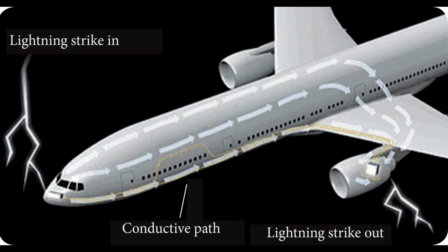In a composite aircraft, fiberglass is an excellent electrical insulator, while carbon fiber conducts electricity, but not as easily as aluminum. Therefore, additional electrical conductivity needs to be added to the outside layer of composite skin. This is done typically with fine metal meshes bonded to the skin surfaces. Aluminum and copper mesh are the two most common types, with aluminum used on fiberglass and copper on carbon fiber. Any structural repairs on lightning strike protected areas must also include the mesh as well as the underlying structure.